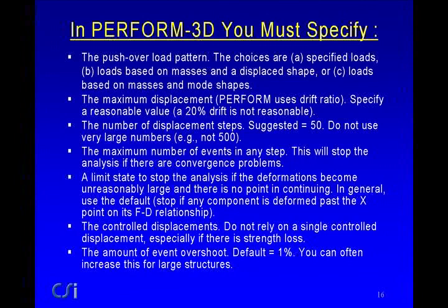Then a limit state to stop the analysis if the deformations become unreasonably large. The structure can start to collapse or something like that, and you get some very large deformations. There's no reason to continue the analysis beyond that point because something has gone wrong. Either your model is wrong or something like that. If you recall the force deformation relationship in Perform, it is this YULRX, and X is a large displacement beyond which there really isn't much point in continuing the analysis.